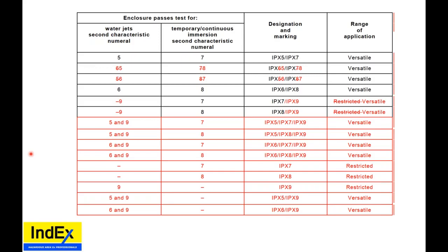Will all EX certificates include the IP rating? I've seen some ATEX equipment that does not include the IP rating. Under the IEC standards, yes, they shall list the IP rating and shall have IP testing. If they don't, that's possibly going to cause the manufacturer to not be able to sell their equipment to certain end users, or procurement people will question their IP ratings.